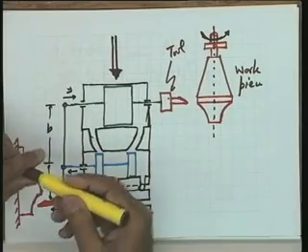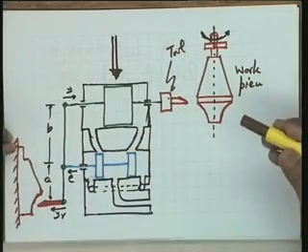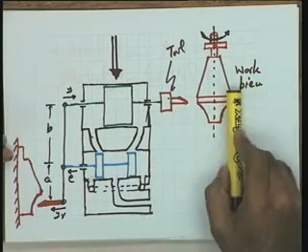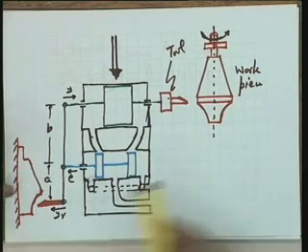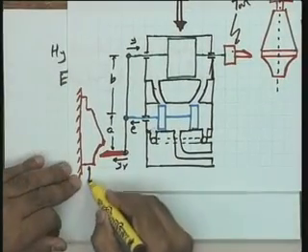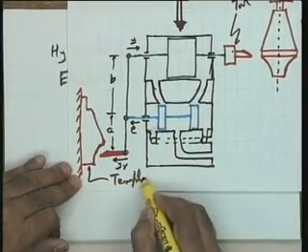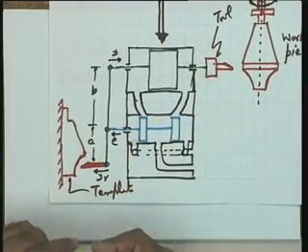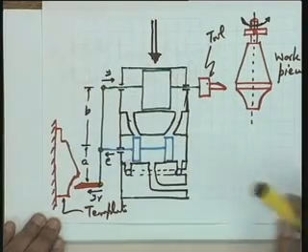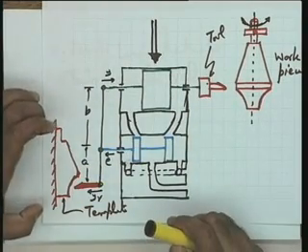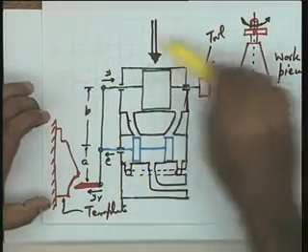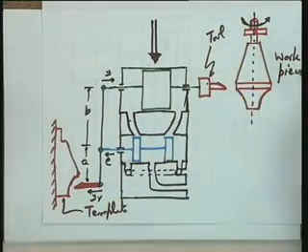The idea is this, please see the requirement: the depth of the tool should be controlled in accordance with the job to be done, and the job to be done is shown on a template. So, actually I want that this workpiece profile should exactly follow this template. It means the template is a command, and this command is to be reproduced on the workpiece, and in between I have this servo mechanism whose action we have to see.